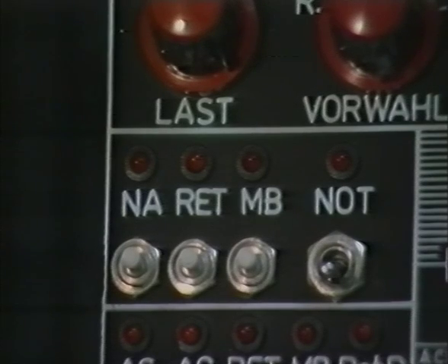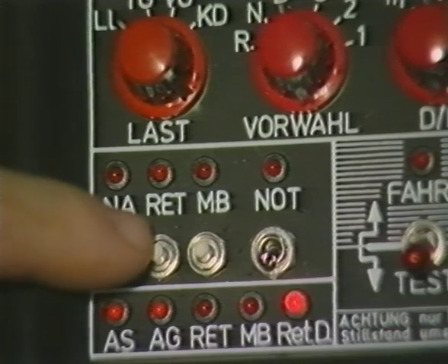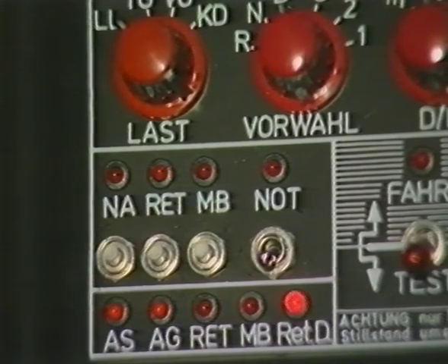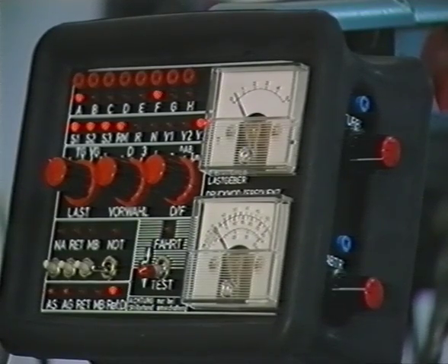If no lights come on, operate this button, which replaces the switch signal from the foot brake. Should the lights come on, there is a fault in the switch or cable. Alternatively, if no lights are on, there is a panel failure.